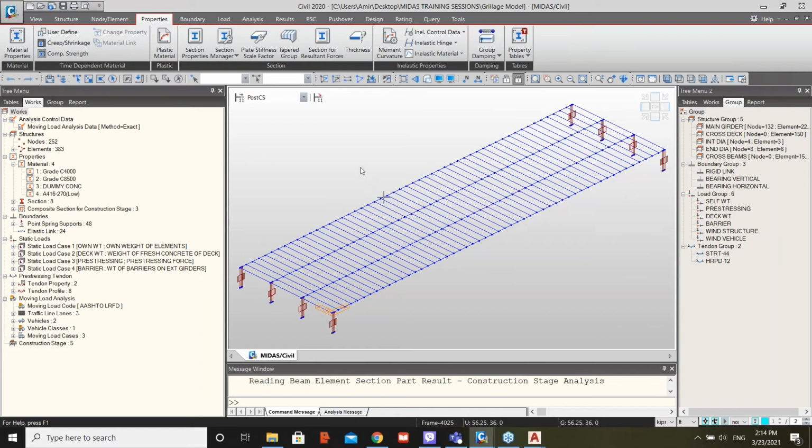This type of bridge is very simple. It consists of a precast girder that can have any shape, an I-shaped girder or a U-shaped girder. And basically you have the deck that's cast on top of it. At some point, the deck and the girder form together a composite section, which means they are completely bonded together and there is no slip between the girder and the deck at the top.